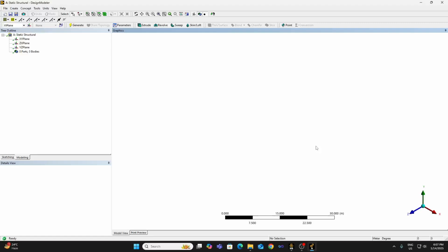You can try both the hardness test and the tensile test simulation using type 1 axisymmetric simulation and type 2 cyclic symmetric simulation. So you can look into Ansys help doc for how to model a cyclic symmetric problem. So you can do that from there.